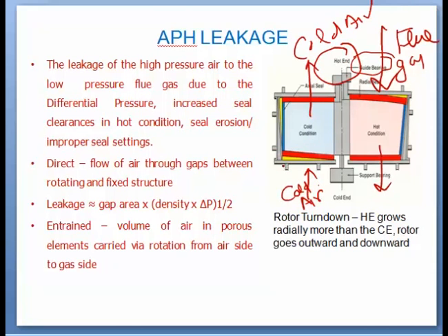So on this side it is cold air, and the temperature is less. Even the flue gas, after transferring its heat to the cold air, comes out at a lower temperature. So this end is known as the cold end, and this is your hot end.